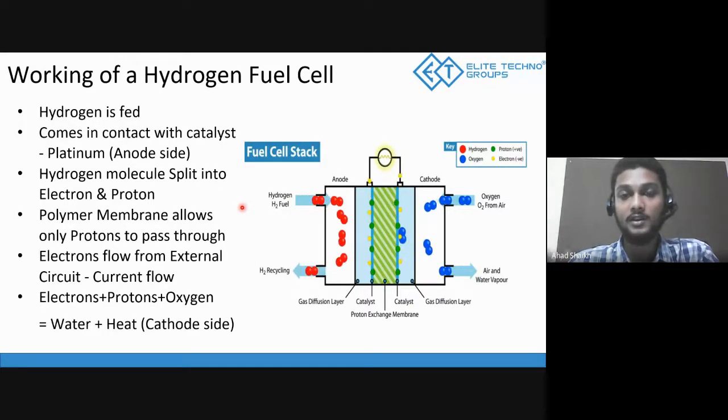One fuel cell stack generates less than 1 volt of output, which is very little, so that's the reason we have to put a lot of stacks in one entire fuel cell. If we compare it with our regular lead acid battery used in the current automotive industry, one cell gives around 2 volts, and that's why we put 6 cells in series to get 12 volts as output.